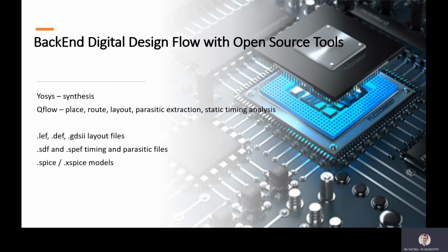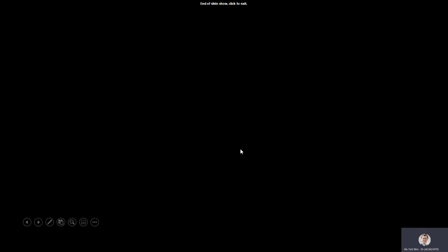And finally, I'd also like to highlight to your attention that the tools also generate equivalent SPICE circuit models, which you can then run through a SPICE simulator to get a more precise, analog circuit level simulation of the chip's performance. But as you can imagine, this step is more of a sanity check step. We typically do not run most of the verification tasks in SPICE simulators because this would take too much time. So without further ado, let me jump straight into the proposed tool setup that I prepared for this lesson.